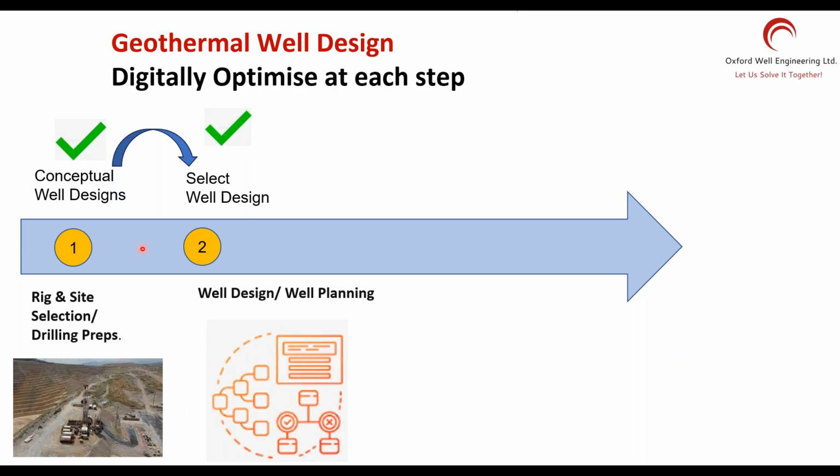You will check on previous wells, how they had been designed, and also see how they had operational problems. For example, if you had problems in the curve part of the well, in the curve they had all kinds of issues, hole cleaning issues, difficulty running strings, or maybe collapsed wellbores. How about reducing the tortuosity in the curve section?